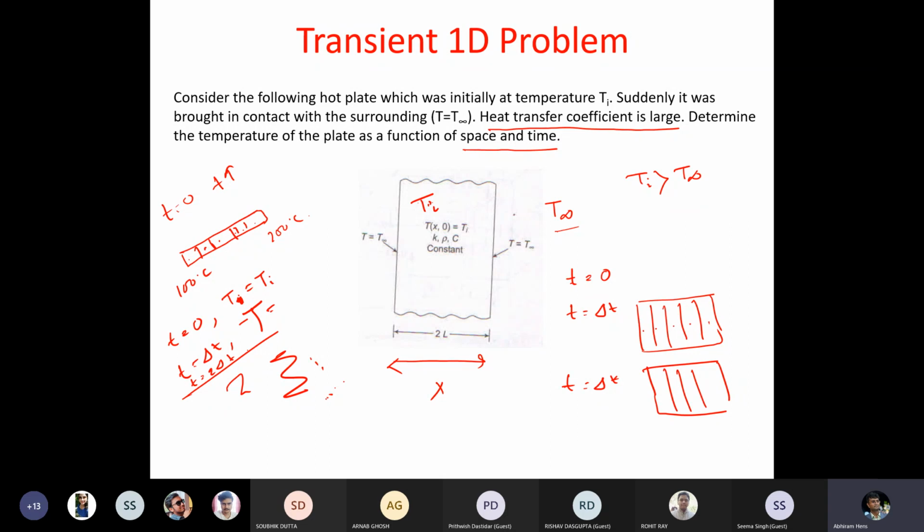Okay, so the approach of CFD, the steps of CFD, are that the first step is to identify the geometry, right? So here the geometry is given to you. So this is the geometry. Now the moment the geometry is given, you try to look into it and find out if there is any symmetry in this figure. Okay, because it is not always necessary to compute the entire domain. That is unnecessary. You should not increase the computational time.